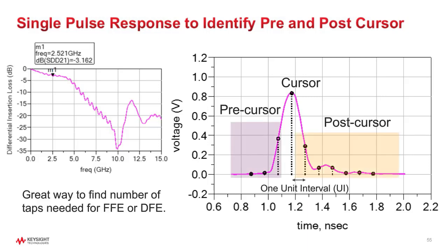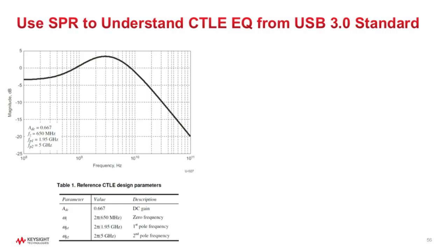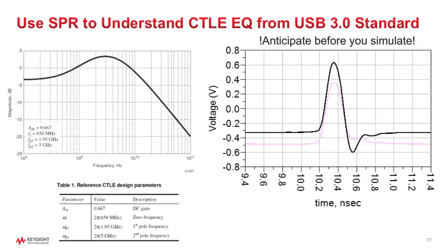And here's after CTLE. We see that horizontally, the timing does not really change, which means that CTLE doesn't really help us on the jitter, especially ISI jitter. But what it does do is, if you look at the minus here, it does take out some of the leakage from the main pulse. And that's how it's contributing.